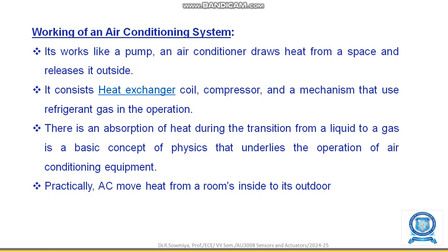Let us see the working of the air conditioning system. It works like a pump. An air conditioner draws heat from the space and releases it outside. It consists of a heat exchanger coil, compressor and mechanism that use refrigerant gas in the operation. The absorption of heat during the transition from liquid to a gas is a basic concept of physics that underlies the operation of air conditioning equipment. Practically, AC moves heat from a room inside to its outside.